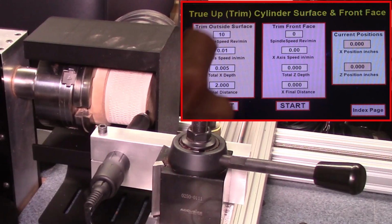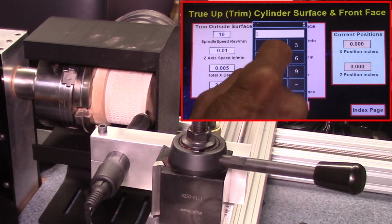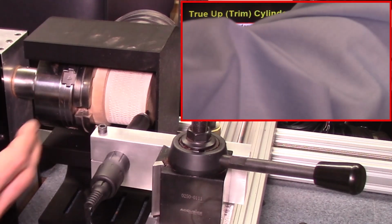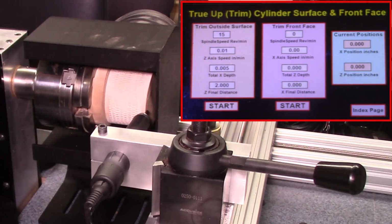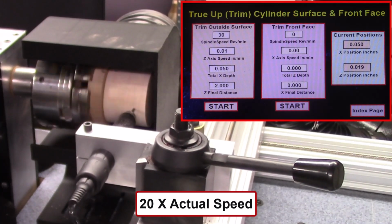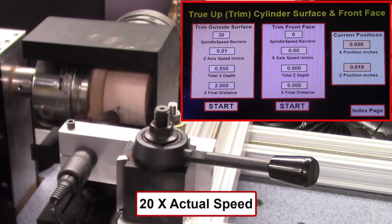So let me speed up this revolution on the outside cylinder. Let me see if I can make it 15 revolutions per minute. And my z-axis movement is 0.01 inches per minute. So it's moving real slowly in this direction and turning quickly. So it should give you a nice smooth surface. I sped this section of the program up 20 times the actual cutting speed to reduce your viewing time. Each time I went down about 1/10,000 of an inch until the surface was perfectly clean.